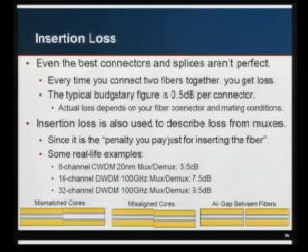Kind of the three ways that you can screw up the connector process is, number one, when you have mismatched cores, like if you plug a single mode into a multi-mode fiber, they're not going to match up. If you have misaligned cores, if you have a fiber connector that's not seated right or whatever. And then if you have an air gap between fiber, that's going to give you a lot of signal attenuation if you don't have the fiber completely seated, if you don't have a clean mating.